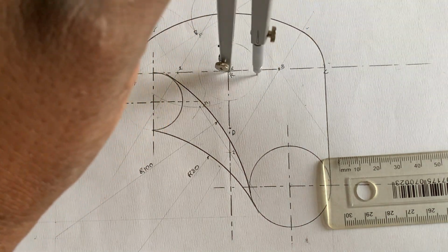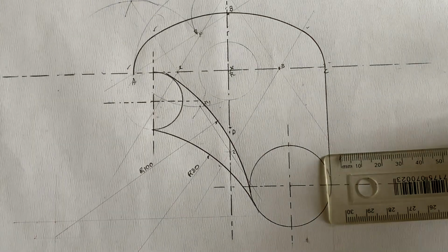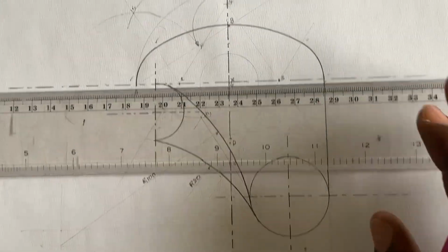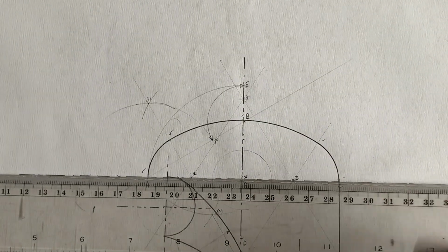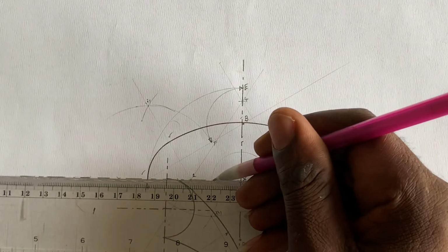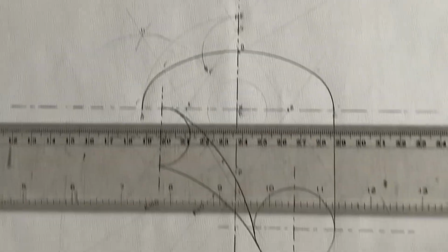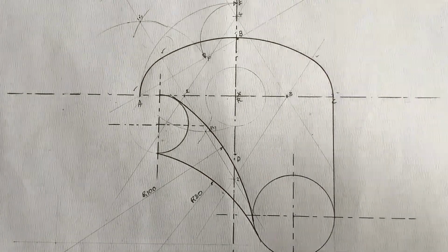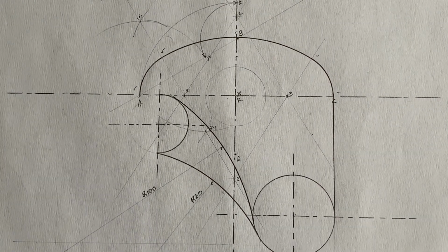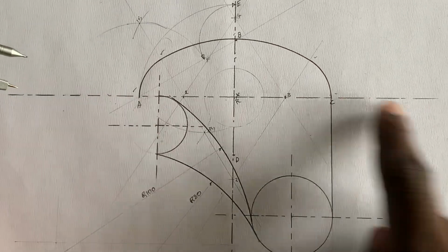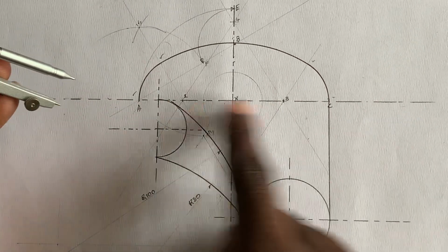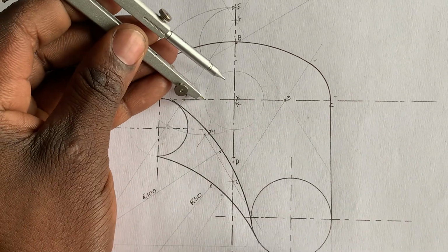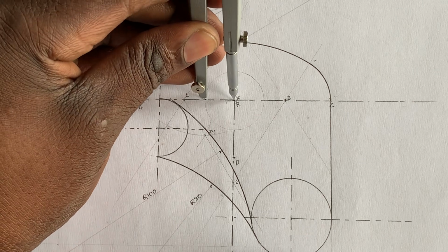You draw it faint because it's not part of the hexagon. So now I can come, let me get the exact point there. You get it? So from there, you take a drawing compass. Since you want to obtain a flat hexagon, you're going to stick on the horizontal center line. You place it here, further extend it to the center. This is it.